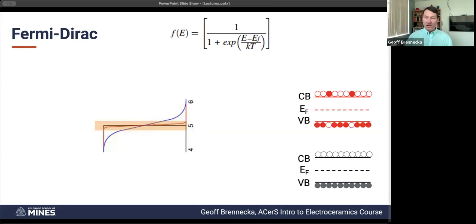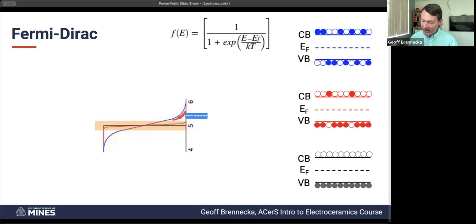As we heat things up, we're going to get a few more electrons that are populating these higher energy states, and they're leaving behind holes in those lower energy states. And so when we get to high enough temperatures, these electrons have enough thermal energy to jump across that band gap and populate the conduction band. And that's just represented with this population. So the Fermi-Dirac statistics, all it is telling you, here's where the electrons are going to live based on the temperature and the Fermi level, the energy of that gap. That's all we're worried about.